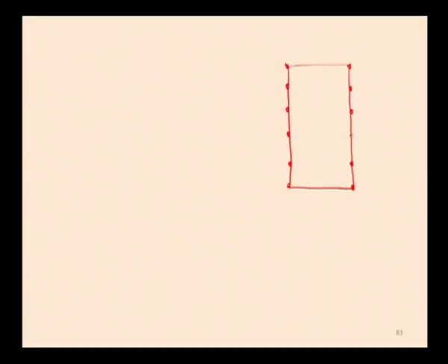Now, how to provide the slab system for this case? Normally, we connect the columns by means of beams and provide the slab over these beams. So, this is the longitudinal section of the slab which is supported over the beams. These beams are normally designed or analyzed as T or L beams. So, the intermediate beams are designed as T beams.